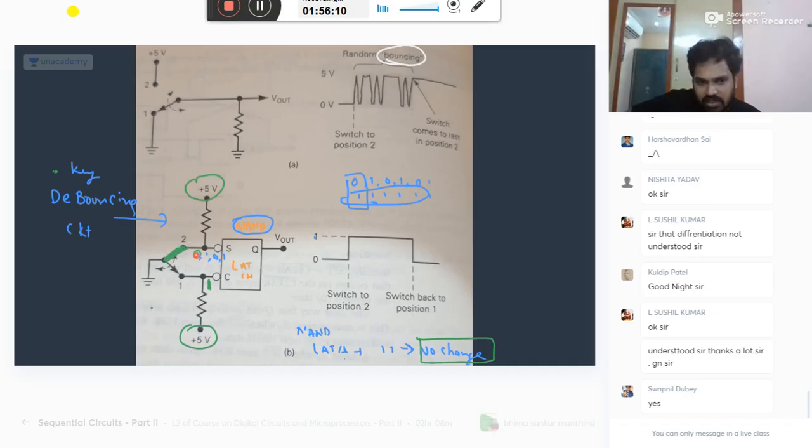By chance, if this has some loose connection and it becomes 1 also, no problem. Once you give the input 0, it will give you output set. After that, because of a transient, if it has toggled for some time, no problem for me. It becomes 0, 1 anyway, because 1, 1 also gives me the same output.